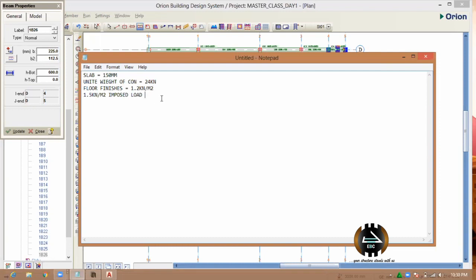So now, I'm going to go down a bit. Let me show you, okay, let's calculate our load. So we already know that our W is equal to 1.4 GK plus 1.6 QK. We are conversant with this. So you want to generate your W, 1.4 of your dead load plus 1.6 of your live load.